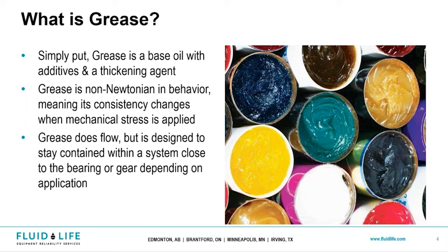And there are obviously techniques that you learn, especially on the sampling side, where consistently you can get a better representative sample. So right there, you want to look towards the load regime of a bearing. And where you'd see that is technically the hardest spot to get to, but you yield the most accurate results when you do that.